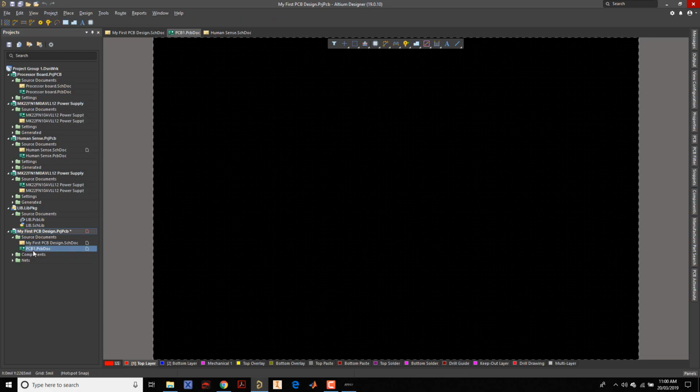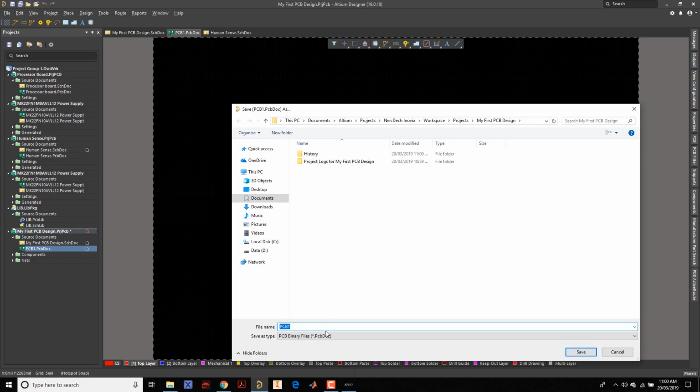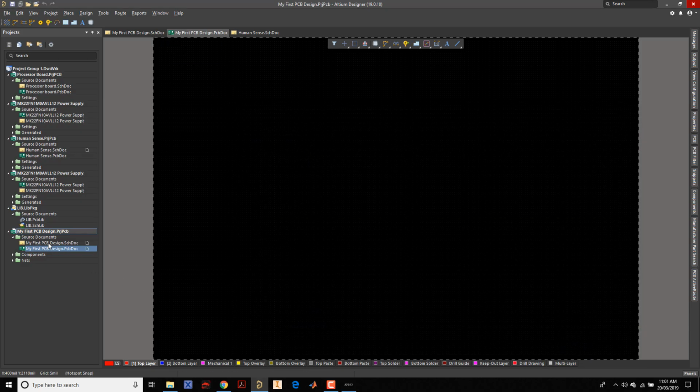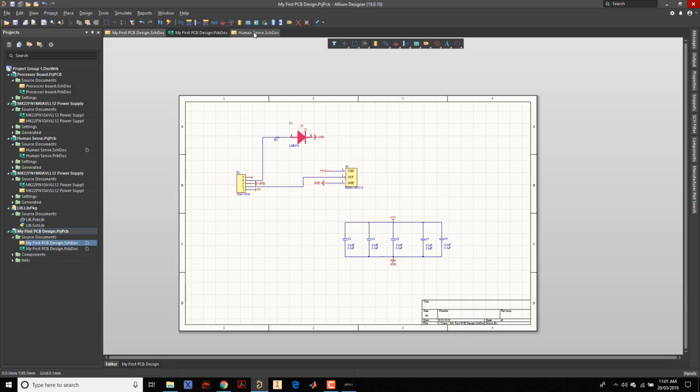Okay, so you see it creates it. I'll save it with the same name, right? Just add my, alright, and then remove the extension and it will name it .pcb. So you see my first PCB design .pcb doc. Alright, so now I'm here. Okay? Good. So let me just close this. Alright, now I'll compile again.